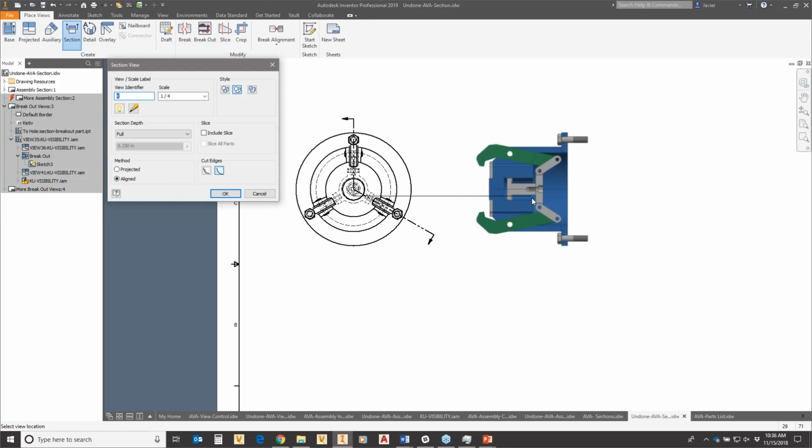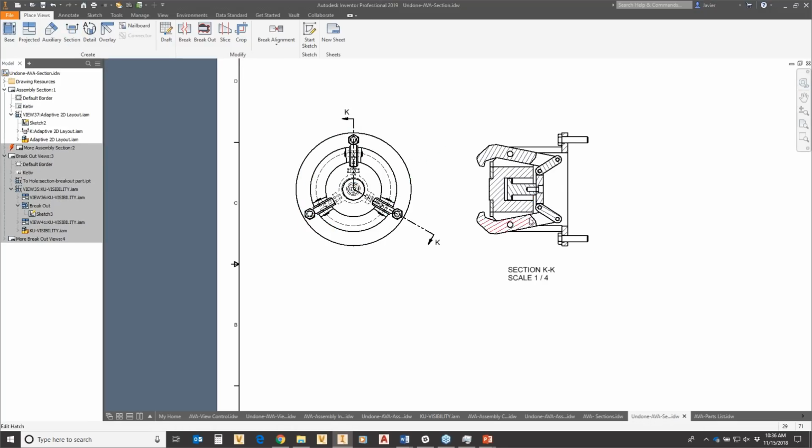And as I drag this to the right, you'll notice that it takes this fastener and shows it at the very bottom. It takes this entire line and rotates it this way. Okay, that's a little bit different, right? What that allows you to do is dimension a little bit differently in this section view, and you would probably put a note that says it's a rotated view.